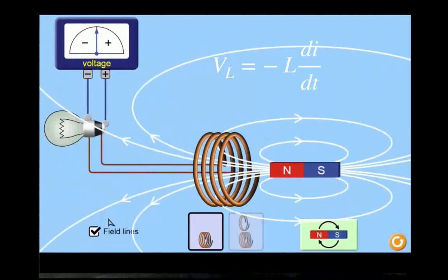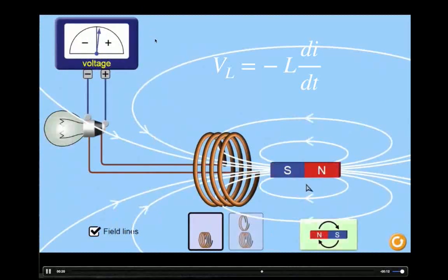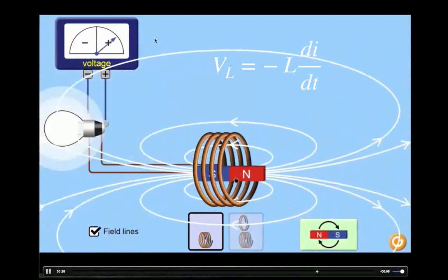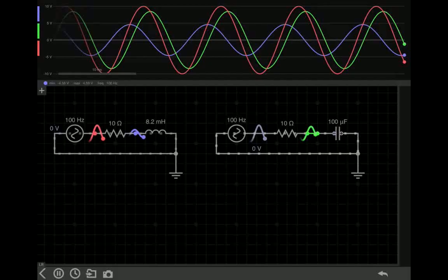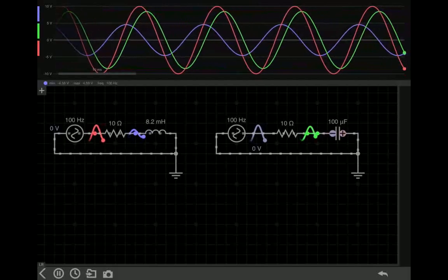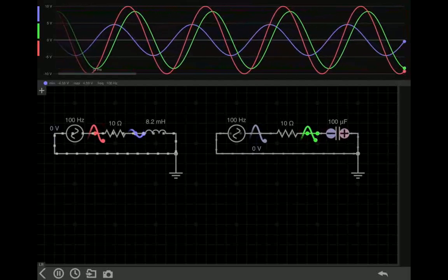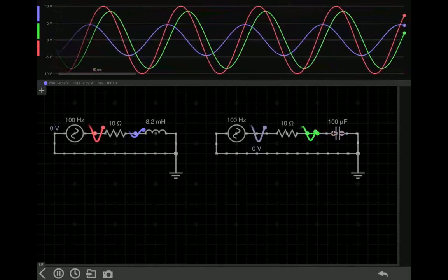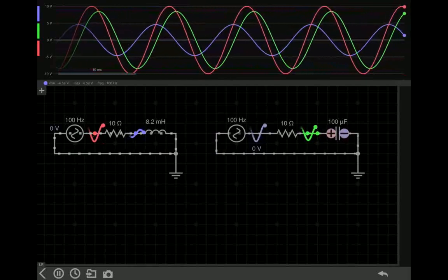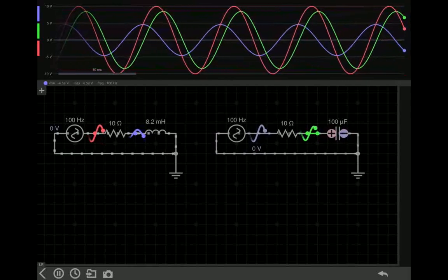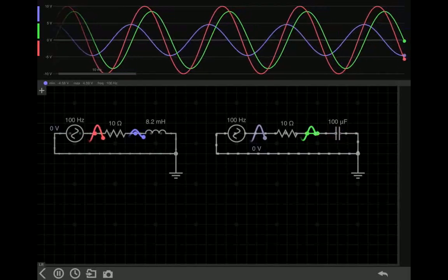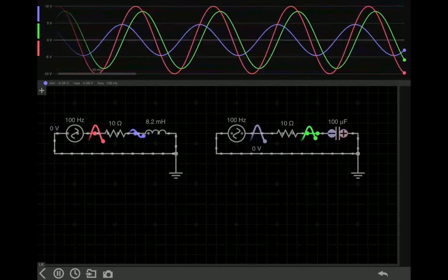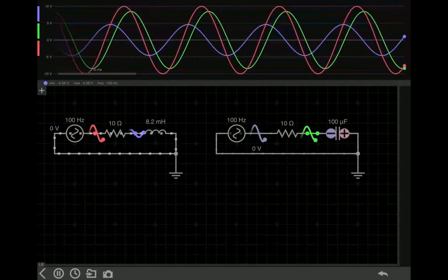This virtual lab will give emphasis to the AC domain of the so-called resistor-inductor circuits, where most of its practical applications are found. The coil, or inductor, exhibits the exact opposite behavior than that of a capacitor. A cap, because it cannot charge instantaneously, exhibits a lag with respect to the circuit's voltage. This essentially means that the cap's voltage is maximized after the circuit's voltage, simply because it needs time to store the charge. We have observed this behavior in our previous lab.